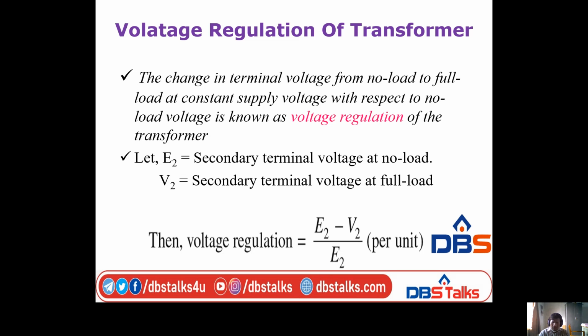This is the most important point from the competitive examination and GATE examination point of view. The voltage regulation varies with a leading power factor, that is positive, negative or zero. For unity and lagging power factor, it is only positive.